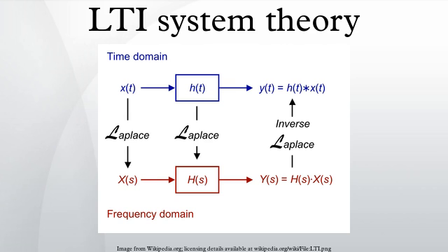Fourier and Laplace transforms. The eigenfunction property of exponentials is very useful for both analysis and insight into LTI systems. The Laplace transform is exactly the way to get the eigenvalues from the impulse response. Of particular interest are pure sinusoids. These are generally called complex exponentials even though the argument is purely imaginary. The Fourier transform gives the eigenvalues for pure complex sinusoids. Both of them are called the system function, system response, or transfer function.